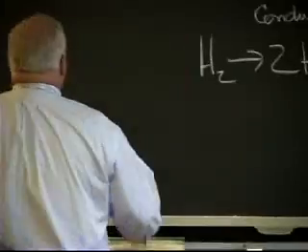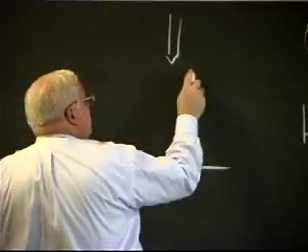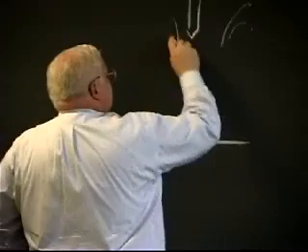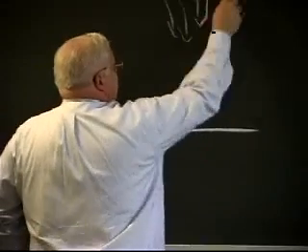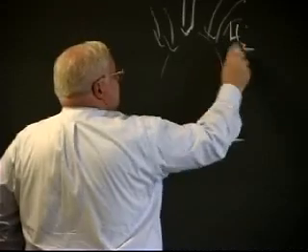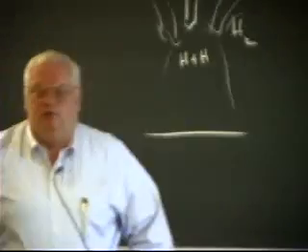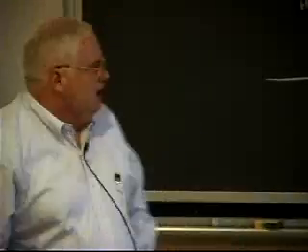So if I'm up in the arc over here, and I have some hydrogen in my arc, the hydrogen is coming in from the side, from the shielding gas as it blows in. In the heat of the arc, that diatomic hydrogen is dissociated into monatomic hydrogen.